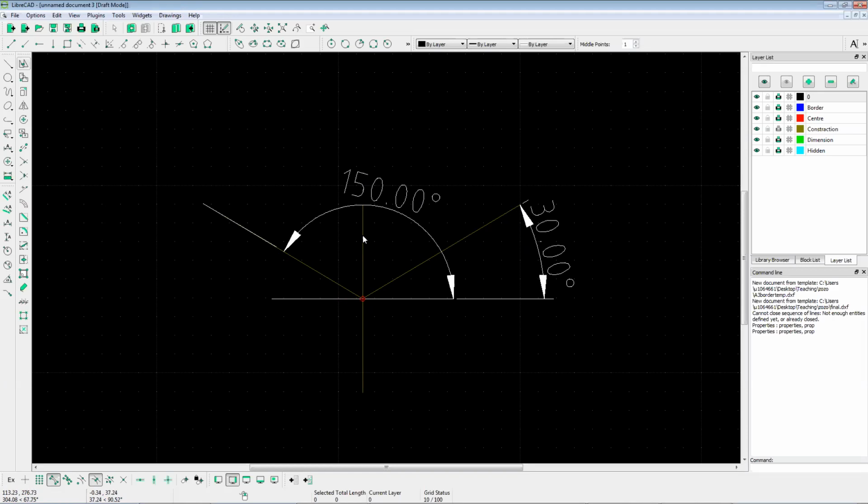So this is to draw a vertical line, and this is to draw a horizontal line. The case always will be, if you're drawing a line in this direction, it will be by 30 degrees. While if you're drawing a line in this direction, you will do it at 150 degrees, which is still the same 30, but in the other direction.